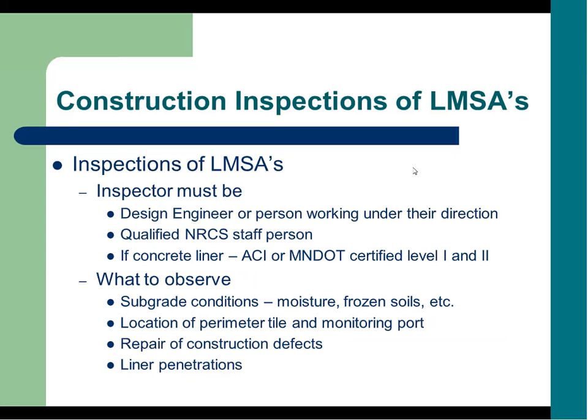Inspections of the LMSAs. The inspector must be a design engineer or person working under direct supervision of a PE, or qualified NRCS staff, and if it's a concrete LMSA, the person doing the testing should be ACI or MnDOT certified level 1 and 2. What you need to observe while you're out there: subgrade conditions, is it too wet, is it frozen, do the soils not look like what the borings indicated, locations of the perimeter tile and the monitoring port, repairing the construction defects if they're found, and potential liner penetrations.